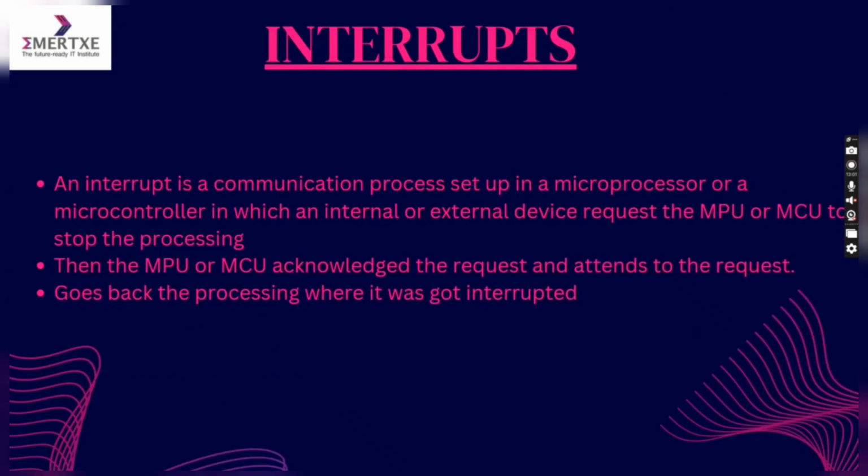Next is interrupt. An interrupt is a communication process set up in a microprocessor or a microcontroller in which an internal or external device requests the microprocessor or microcontroller to stop the processing. Then the microprocessor or microcontroller acknowledges the request and attends to the request. Then it goes back to the processing where it got interrupted.